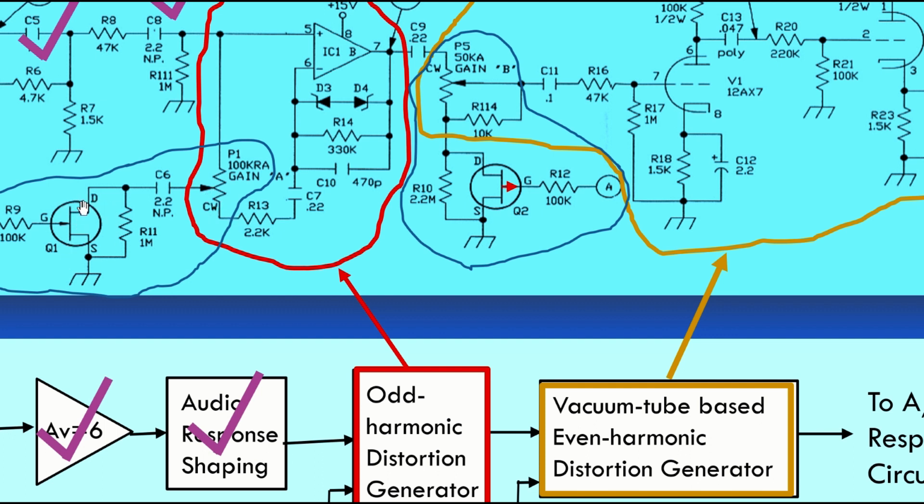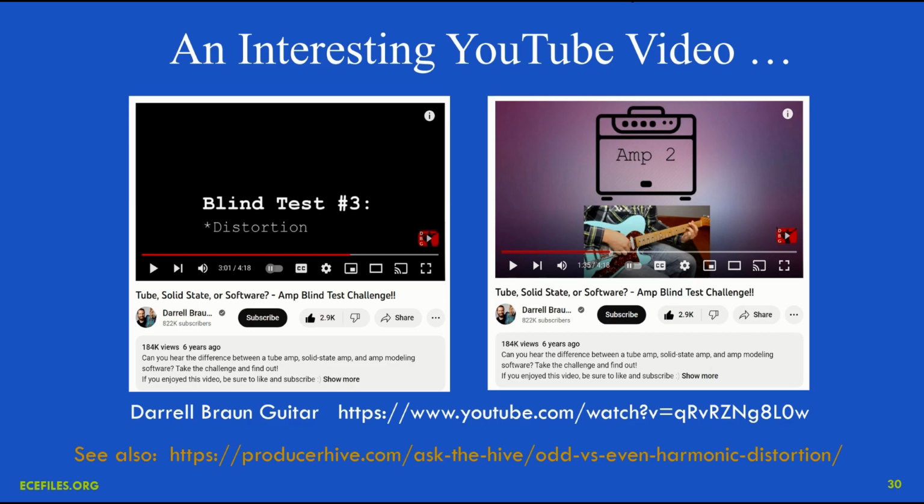This is playing the role of what's called an analog switch, and if we turn off that analog switch, then this is no longer AC grounded, and this reduces to a gain of about 1. At which point, the main gain is supplied by these vacuum tubes. And why are they there? Well, everybody loves vacuum tubes, for one thing, if you're in audio. And what is the reason for that? Well, they produce a different kind of distortion, usually termed in the literature even harmonic distortion. And we'll take a look at that.